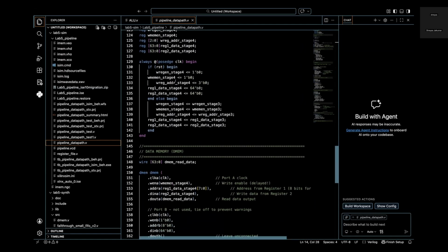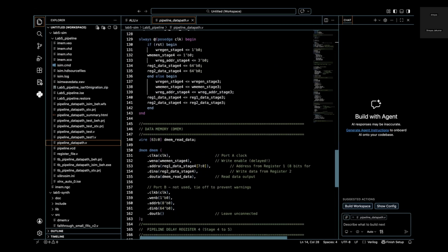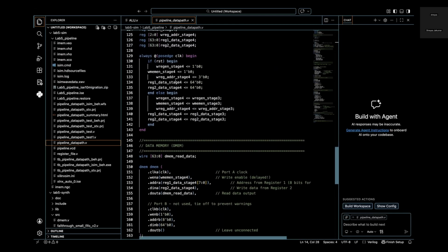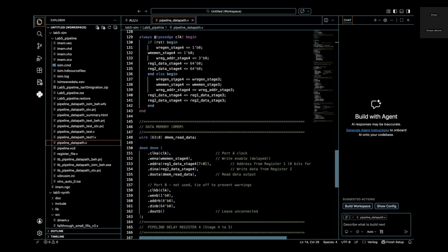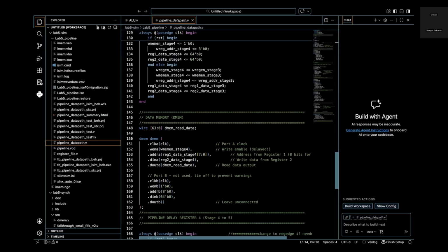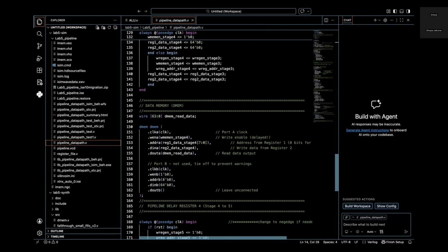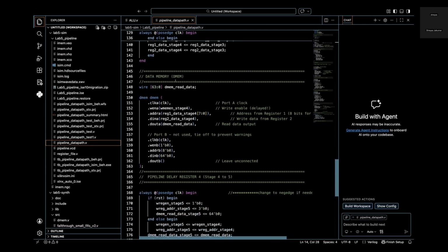the write address is being propagated entirely through the pipe until the last write back stage, and then that is connected to the register file because that has to be 4 cycles late in order to ensure synchronization, so that the write happens to the correct register address and not the instruction that enters the pipe. Otherwise that won't reflect the correct return value, right?